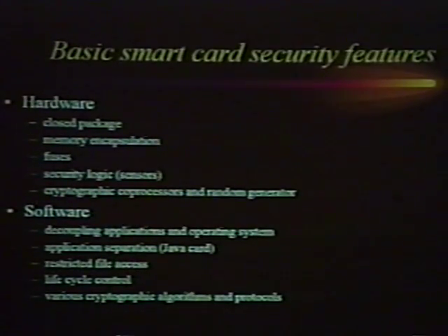There is, like in many operating systems, restricted file access. For every file, first of all, I have to tell you that on the E2PROM, there's just a file system. Like on a hard disk, you can have a file system. You can have it on the E2PROM too. And this file system contains files with access conditions. And for every file, we can set who can access it and what kind of operations we can do on it. Another nice feature is lifecycle control.